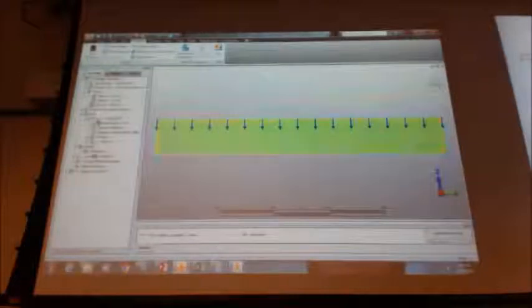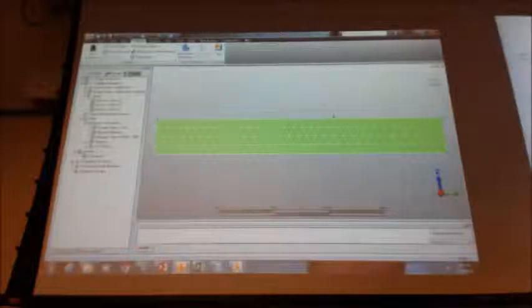Go back here and go to my second design scenario. So anyway, you just reapply your constraints, reapply your loads, and analyze, because everything else stays the same. It's still 2D, it's still 1 inch thick, and it's still mild steel. And then get your values looking at the tensor or the Z deflection, and then you can chart that, and away you go. Does that make sense? Question?